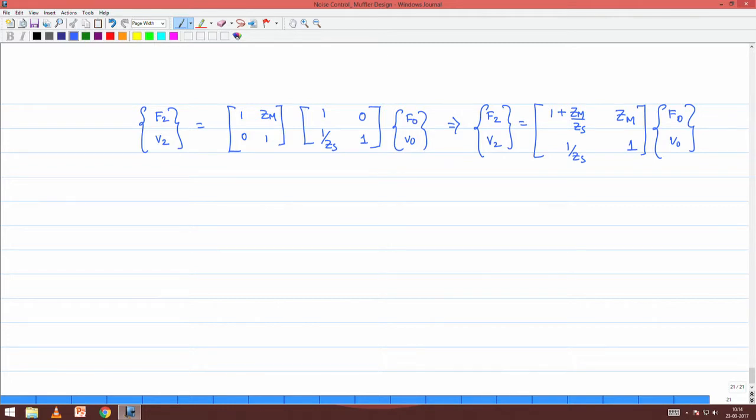The downstream point is station 0 and the upstream point is station 1. Now, from the transfer matrix itself, again we can calculate what is known as the drive point impedance. By drive point impedance, what we mean is the following: we will have this spring and mass, this is mass and this is stiffness, it is being driven by a certain force, it has a certain velocity, and as per our notations, this velocity is denoted by V2 and the force is denoted by F2.